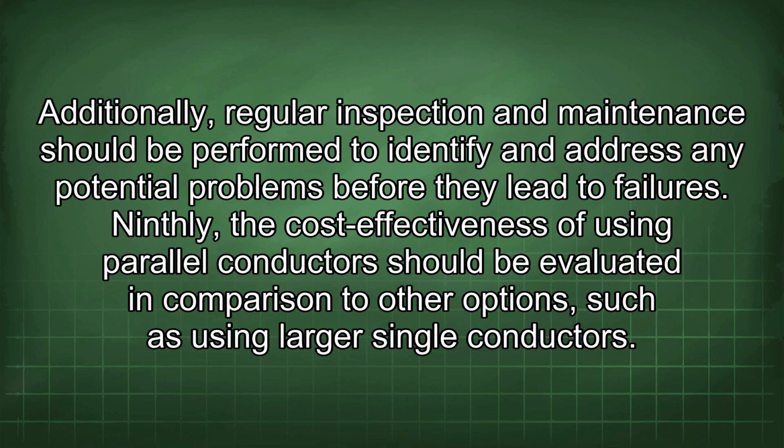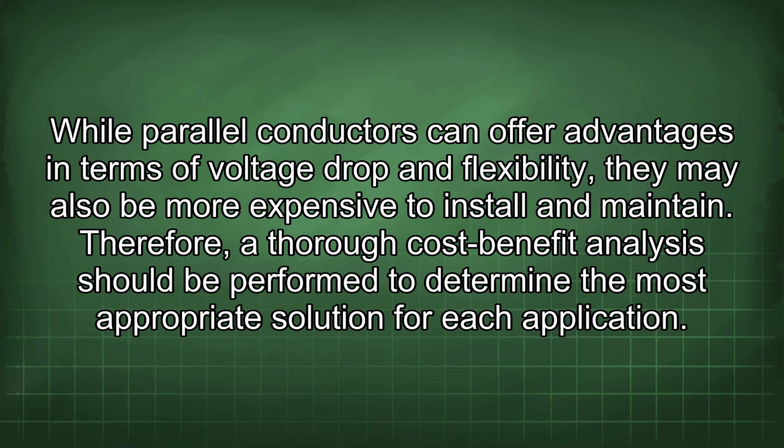Ninthly, the cost-effectiveness of using parallel conductors should be evaluated in comparison to other options, such as using larger single conductors. While parallel conductors can offer advantages in terms of voltage drop and flexibility, they may also be more expensive to install and maintain. Therefore, a thorough cost-benefit analysis should be performed to determine the most appropriate solution for each application.